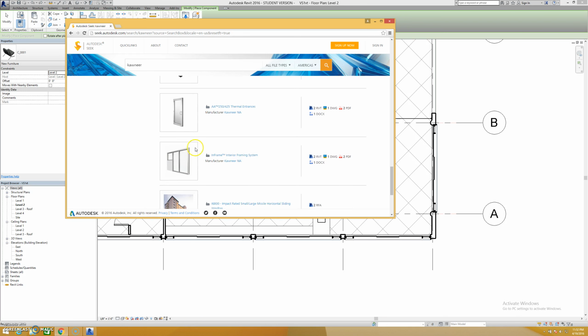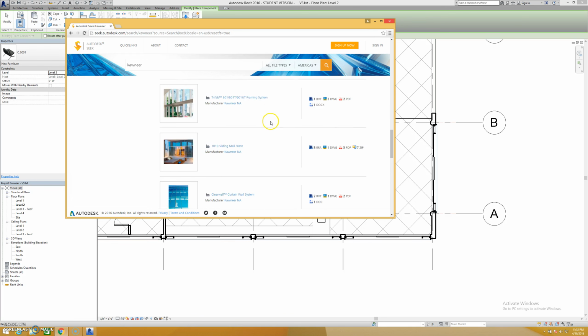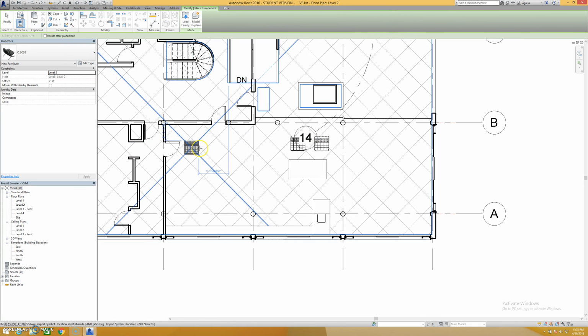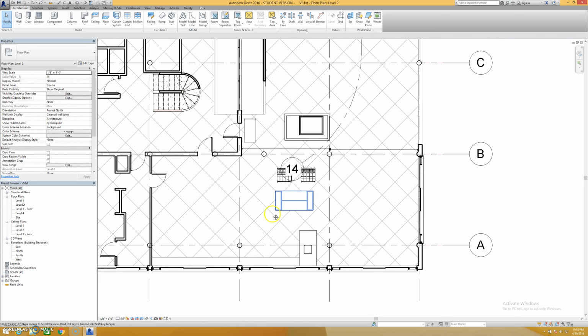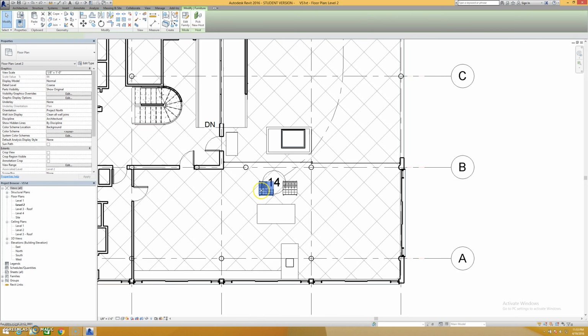So again, if you use Conair systems and it looks like a Conair system and you design with that Conair system in Revit, you know, the likelihood is that you may build it and they may get some money. So they've been really motivated to fill this up with all their different products. So all you'd have to do is create an account, sign in. You can click the RFA and it'll download automatically for you. And open it up and just load it in. Super easy. So that's how you kind of do all that. Furniture is very, very simple.